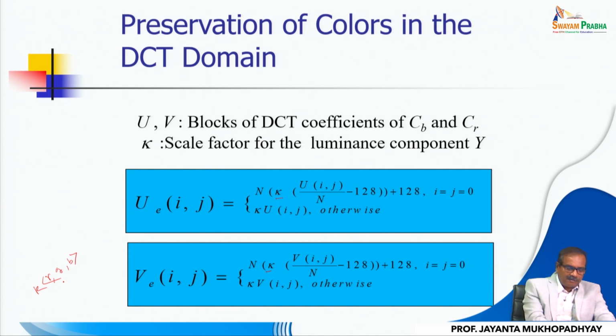The problem of the earlier case is that I was only considering luminance, keeping the chroma part, say the CbCr part, the same without processing. Because the luminance is changing, but the chroma is not, effectively the RGB vectors, this color vector also, there would be deviations.